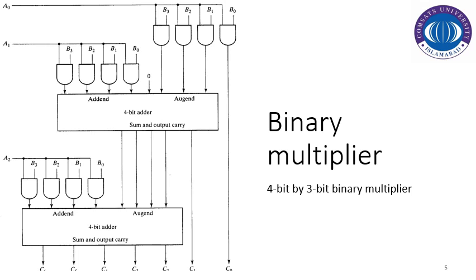and if there is any carry produced in that addition, that should also be used for the addition for the next partial product. The third partial product is achieved by these sort of multiplications, and then the resultant of the addition of the first two partial products, the respective terms, are being added with the third partial product in order to give the remaining multiplication bits.